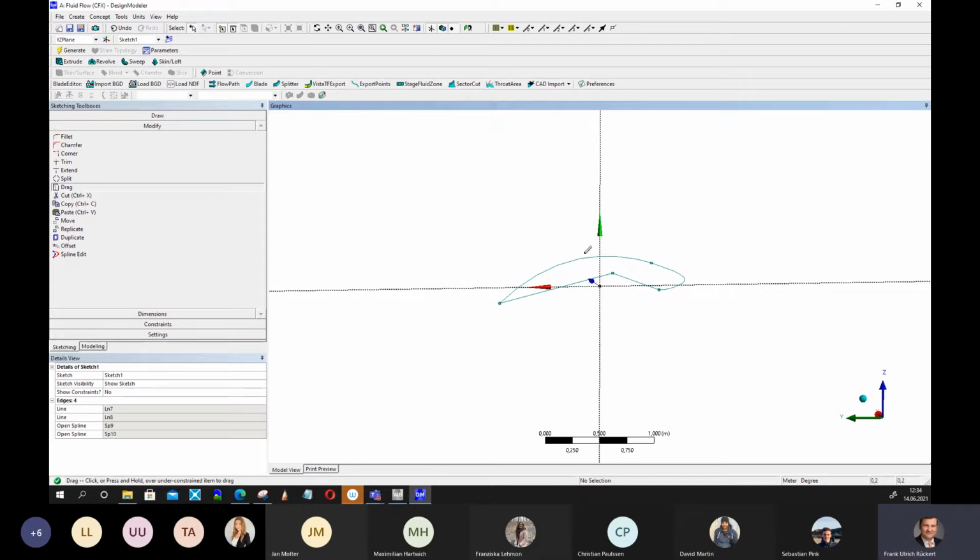And after you've made your rough design of your NACA profile, you know you need a longer way over the wing for higher velocities, and you need a shorter way under the wing for low velocities. Then you will get a low pressure at the upper side and a higher pressure on the side below. And this gives you the force for lift.